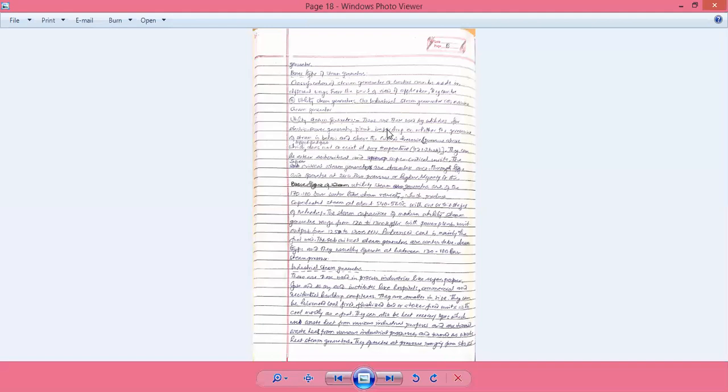What is the difference between these two processes? These industrial steam generators are mostly smaller in size. They are like utility steam boilers. They use pulverized coal and fluidized bed or stoker fired units with coal mostly as the fuel. Generally, only coal is used as a fuel, not any supplement or substitute like fuel oil, because the capacity requirement is very small, and you have to justify the requirement with your cost input. So no other duplicate or emergency requirement is kept here.